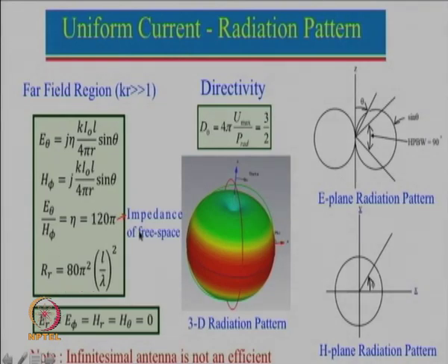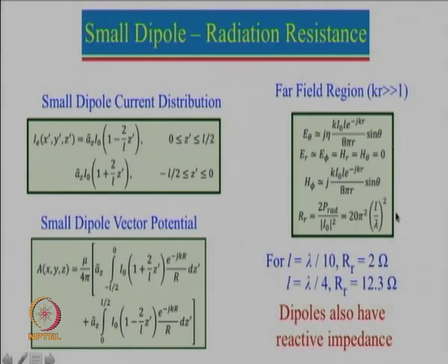And now, you might wonder why I did not talk about this here, because in reality in no situation for a dipole antenna, for a very small dipole antenna, current will be 0 at the end and maximum at the center, with a triangular distribution. So, in general you should not be using this formula at all, but you can see that this value is about 4 times more than the expression which I showed you for a triangular distribution, because I is here increased by 2 times, because there it is triangular, here it is uniform. So, 2 times current increase means 4 times radiation resistance will increase, but please do not use this particular expression even for an infinitesimal dipole. I always recommend people to use this particular expression over here.